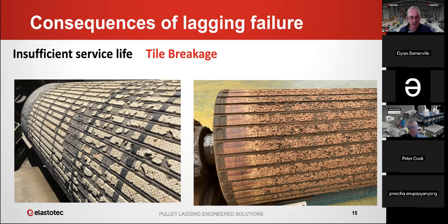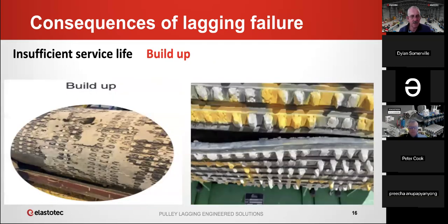The second last one we'll look at is build-up. So this is pulleys typically that are dealing with the carry side of the belt, and excessive build-up can lead to bad belt tracking problems. While you can't necessarily eliminate carryback problems, there are lagging designs that are better at shedding, and so they suffer a lot less from this problem. And we'll talk about those a little bit later on.